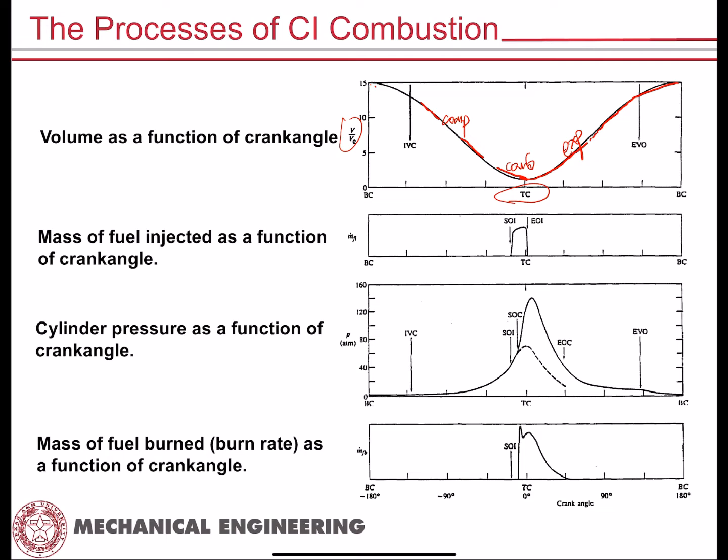Of course, if this were a spark ignition engine, you would be drawing in during your intake process a mixture of fuel plus air, compressing that mixture, releasing your spark, say, around here, and then having combustion and expansion. Well, in a compression ignition engine, you intake air only. So only air is flowing past your intake valves or intake ports, whatever it might be, and you're compressing air only.